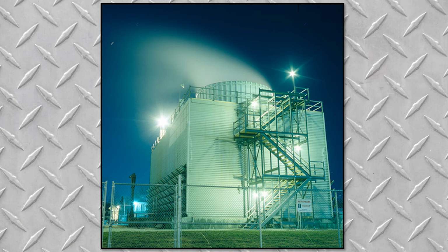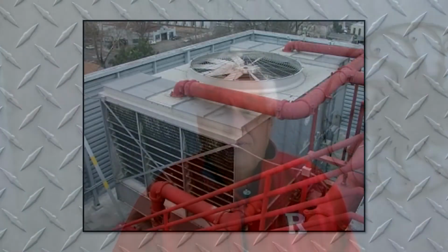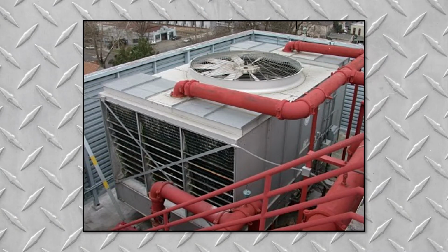Things to keep in mind while placing your cooling tower are questions such as, where is that wet exhaust going out of my cooling tower? It's hot and wet. So is it going into another cooling tower? Or even worse, is it going into the intake of an air compressor or some place where you're trying to dry? Tower efficiency is also dependent upon the physical placement and orientation of cooling tower cells at the facility. If your cooling tower is being blocked by some wall, it's not going to be as effective as if it were out in the open. Although hard to quantify, you should always keep an eye out for things of this nature.